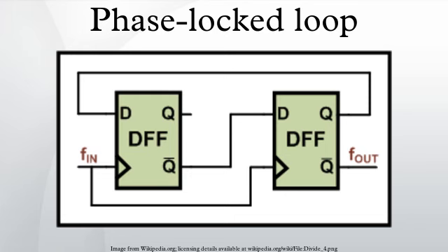Steady-state errors, like remaining phase or timing error. Output spectrum purity, like sidebands generated from a certain VCO tuning voltage ripple. Phase noise, defined by noise energy in a certain frequency band. Highly dependent on VCO phase noise, PLL bandwidth, etc. General parameters, such as power consumption, supply voltage range, output amplitude, etc.